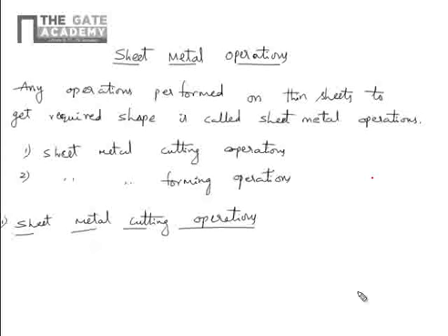From the stress strain diagram, which is very important, this is the yield point and this is the ultimate stress. If you apply load above yield stress, deformation takes place. You apply load above ultimate stress, failure takes place, cutting takes place.